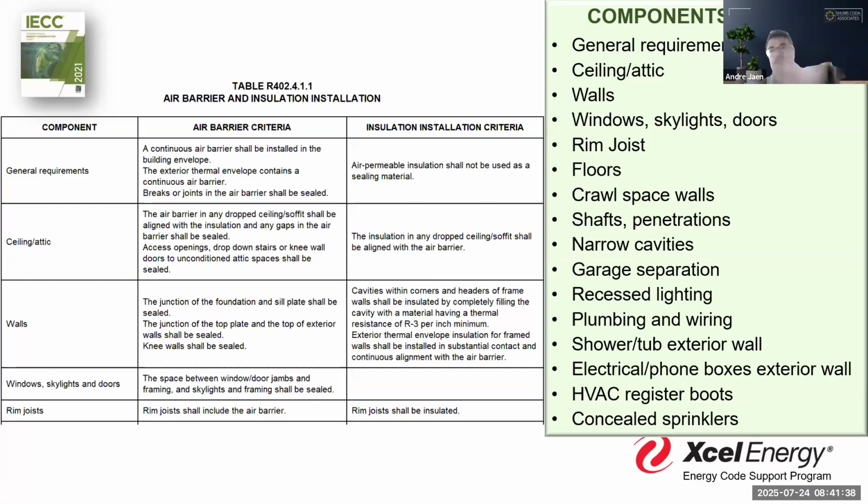Make sure that you have an air barrier that's continuous in those places. But the insulation isn't going to pack in and prevent that. It's just creating thermal bridging. Basically, that's the reason that it was added. But this is your chart that you want to go to, and you want to treat it like your checklist, so to speak, when you're looking at your plans.